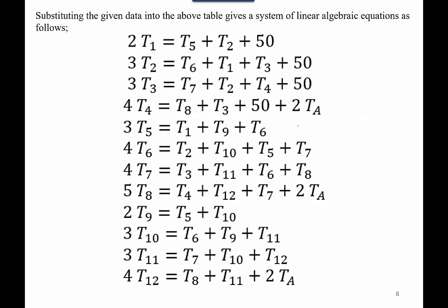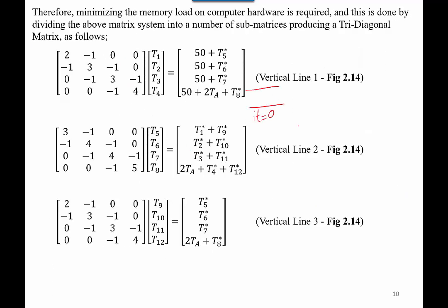Therefore we will assume the whole domain is at 100 centigrade, and it will not matter if we choose another number, maybe minus 13 or plus 260. This will only delay the solution for a while, and after a few iterations it will eventually give you the specific solution. So all the stars we substitute with the number 100.